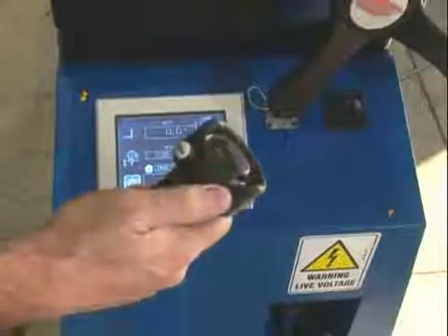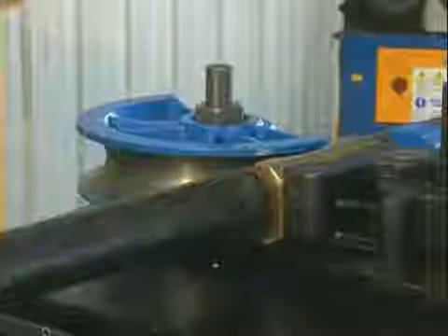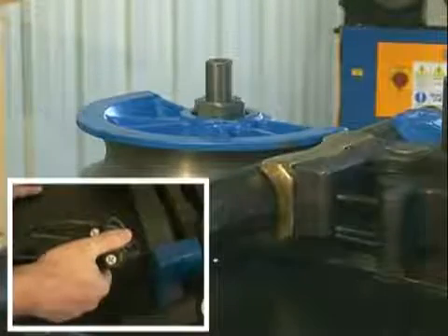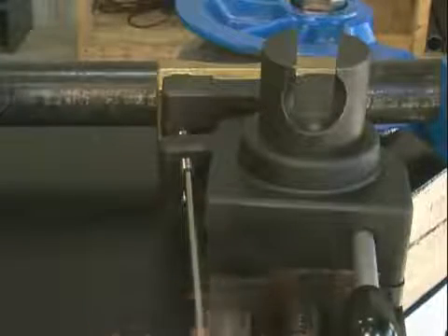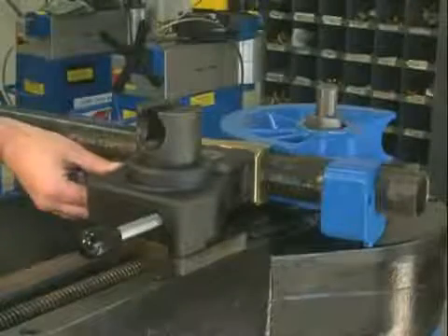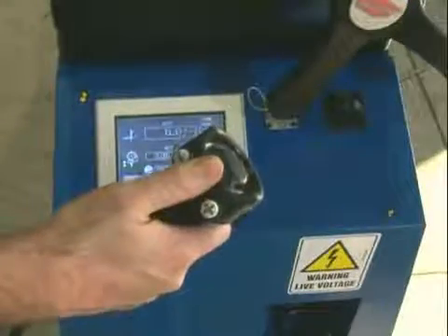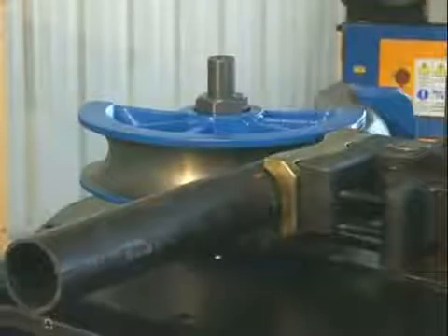The vise base should remain parallel to the machine case. During the first bend to determine material springback, initiate the bend cycle by depressing the plus key on the handheld remote. Stop when the material begins to flex. Using the Allen wrench provided, adjust the vise backing screw to support the vise. Adjusting this screw properly will improve bend quality. Use the locking nut to secure the vise screw. Depress the plus key on the handheld remote to continue the bend cycle. The machine will automatically stop once the programmed angle has been reached.